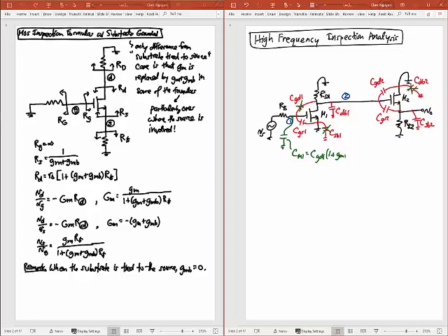And then all this resistance I see out there, I see an R0 going down M1, but I'm going to assume that's big. I see a resistance going forward into M2. That's infinity because it's a MOS transistor. And so the only resistor I'm going to take into account is this RD1. And that's my Miller capacitance hanging off the input node of M1, which I'm calling node 1 there. Okay? But remember, I also have another Miller capacitance that's hanging off of this node, which I can call CM2. And what's that going to be equal to?